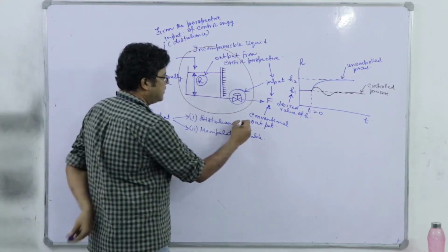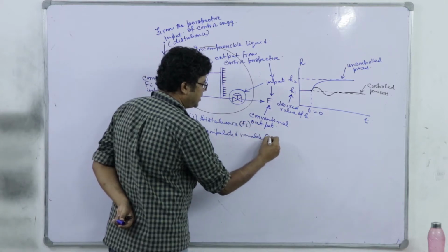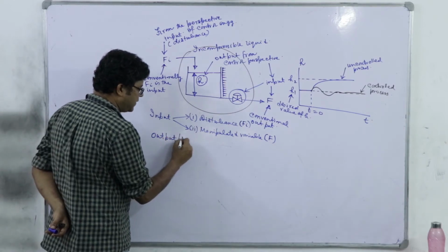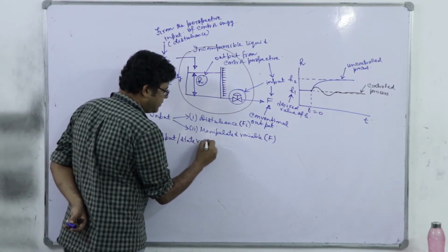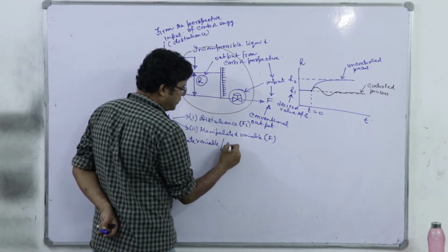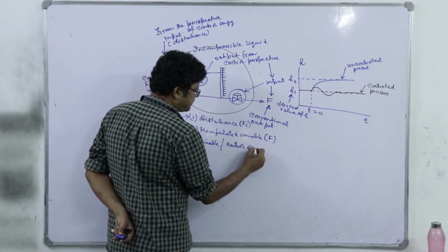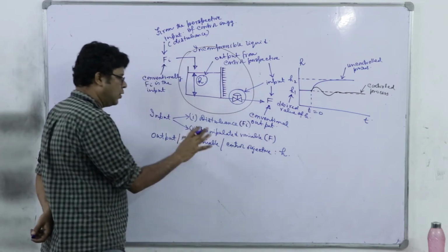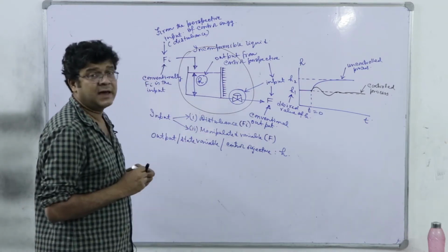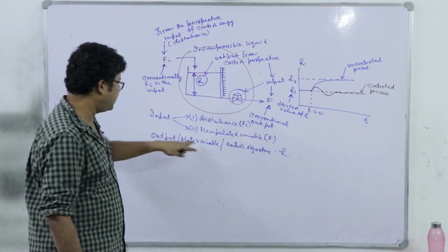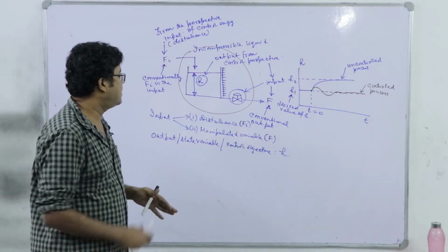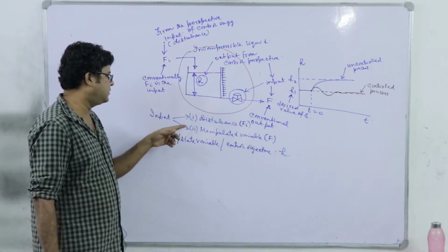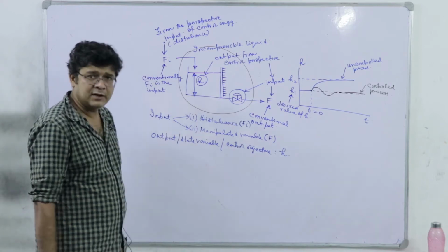So this is the idea of control, and finally here the idea of disturbance and manipulated variable. Disturbance is Fi, manipulated variable is F, and the output, which is also the state variable and also my control objective, is H. You have to note, and we will give an example, that all the state variables may not be my control objective, but all the state variables are definitely outputs.